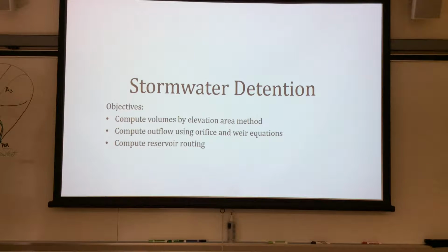Now we're going to talk about stormwater detention. So our objectives are computing volumes by elevation area method. We did that a little bit last week as an explanation, and we're going to review it again this week. Compute outflow for orifice and weir equations. That's going to be new because that's going to be on our control structure, and then reservoir routing. So those are the overall objectives.